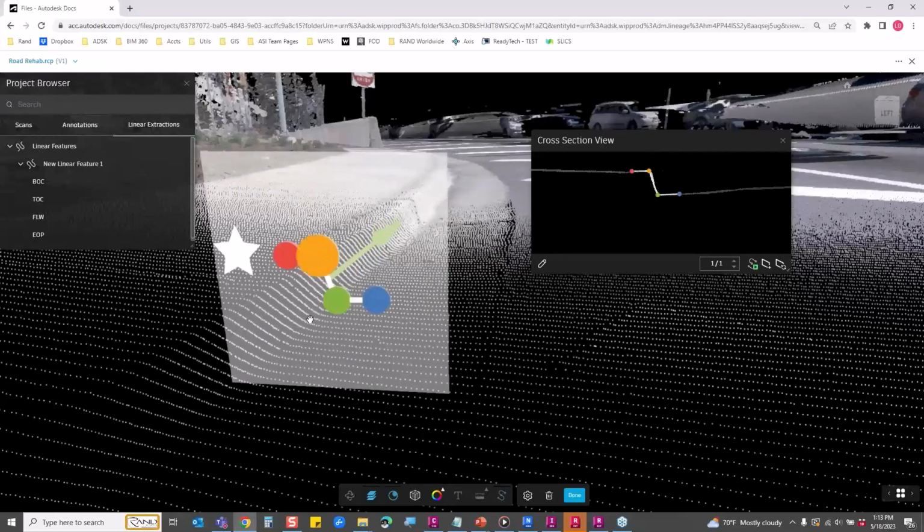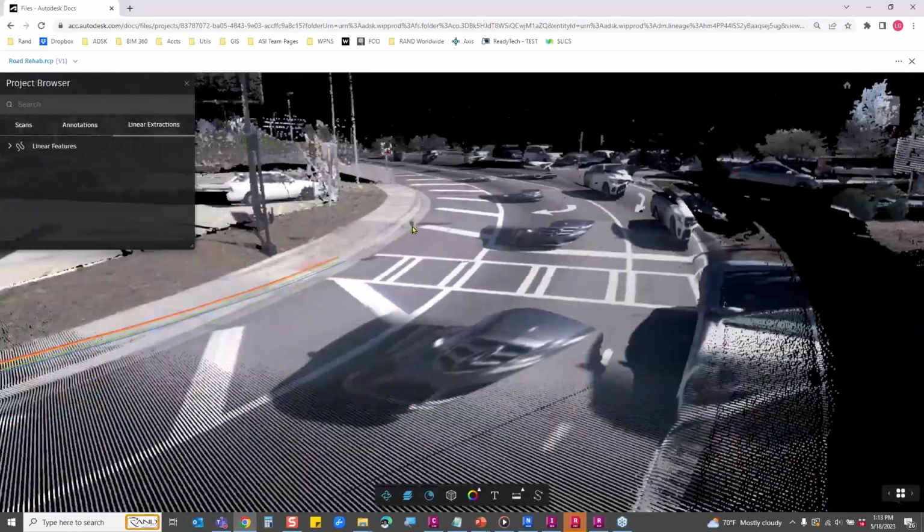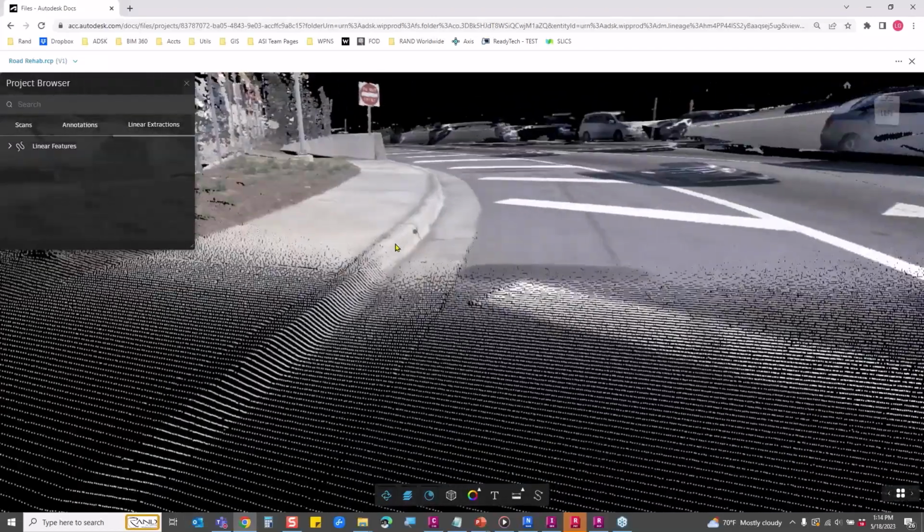And you can see how those points get selected here for me. As I build that typical cross section, I have the ability of calling it done. It's going to run down the list and try to process that line work for me as best as it can to create my feature lines for me on the screen here, that linear extraction. I then have the option of analyzing that design, and it failed on me.